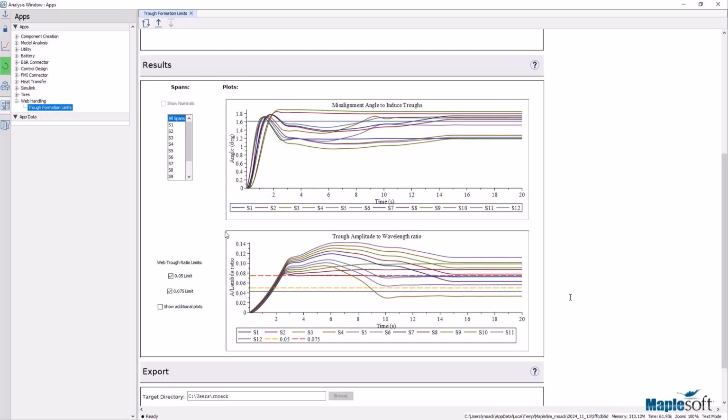Now if you see this, you can check your system, reduce the acceleration if you start the machine, add more torque on your auxiliary drives to reduce the tension, for example, and do other things to avoid overtensioning.